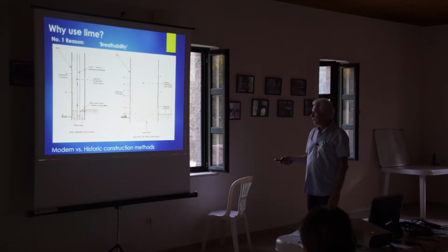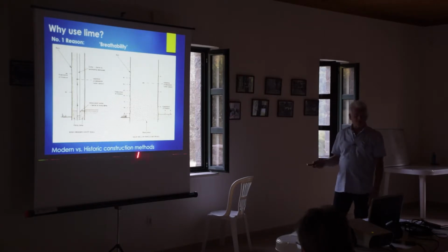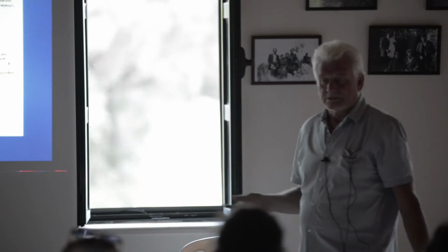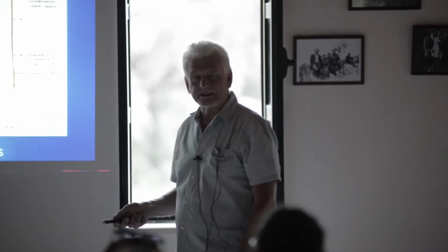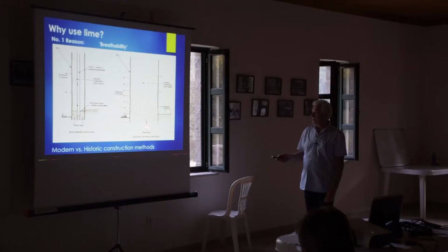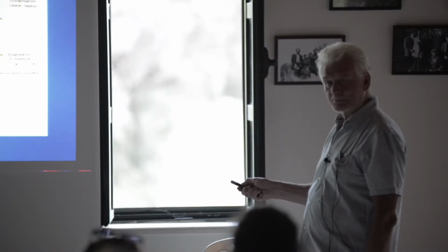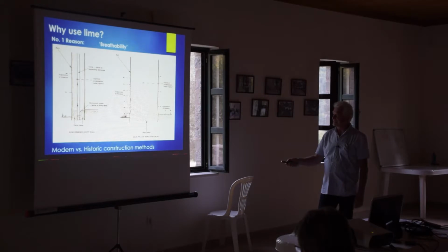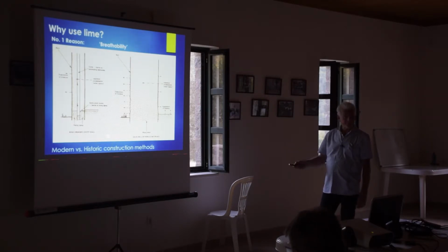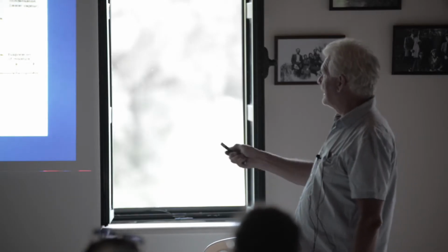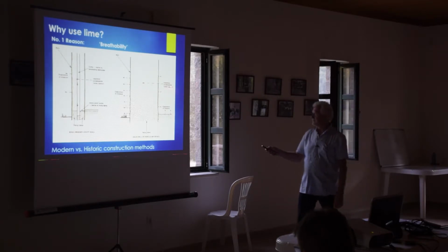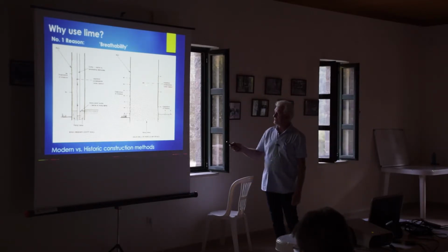On a solid wall of porous materials, let's say clay brick, or let's say stone, this is the old construction. What happens is that the rain will come into the structure, but because everything is porous, including the external render, the water can evaporate. Yeah? And the interstitial condensation, this water vapor, can find its way back out again.